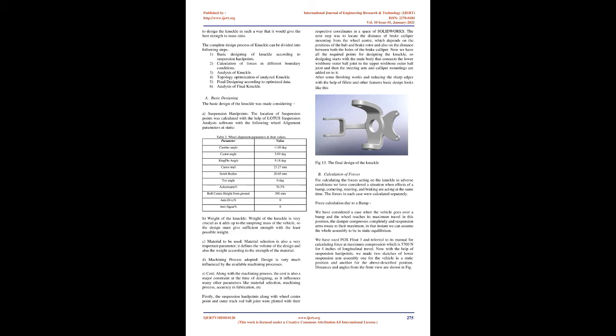Rollover. As we know that the chances of having a rollover are more than that of the front, rear, or side impacts in adverse off-road conditions, analyzing the vehicle against a rollover condition becomes crucial. We have to analyze the vehicle in the worst condition which it can experience at the event, and that is when the vehicle falls upside down from a height, let us say 1 meter. Then from the law of conservation of energy, the impact time taken was 0.15 seconds, as the ground is considered a rigid boundary.